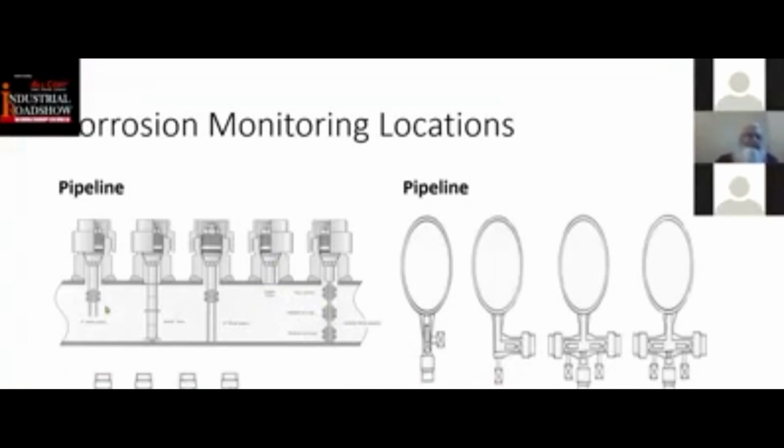These coupons, you see, do have some disadvantage in the sense that downstream of these coupons, particularly the one which goes all the way from one wall to the other end of the pipeline, can create turbulence downstream, which can cause a little bit of erosion there.